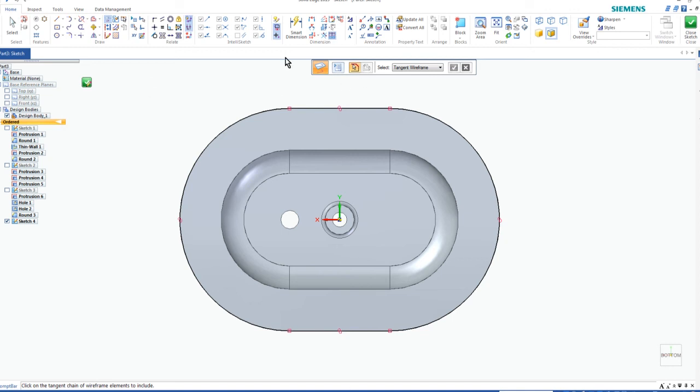That's perfect. So now what I'd like you to do is click on the offset, which is right here. We're going to be using these tools quite often. Here's the offset. If we take a look, the holes are actually located 7.5 millimeters from the edge. So we're going to change the 15 to 7.5, enter.